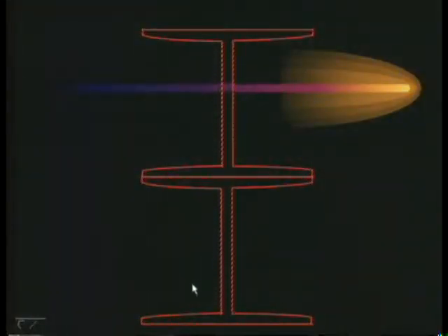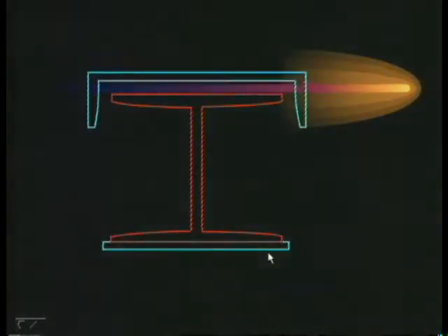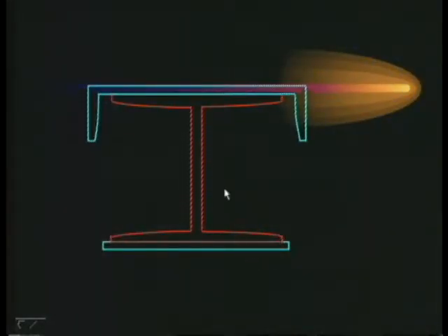Now see this, you need more depth. You have an I section over an I section. So this is a compound beam. Look at this, I section, plate on one side and a channel on the top. Is it not? At this juncture, I would like to tell you the built-up beams are in some cases symmetrical, in some cases unsymmetrical.